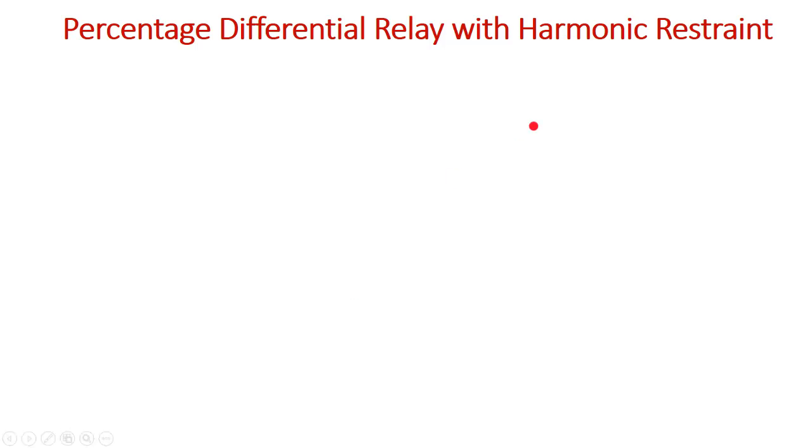What is this harmonic restraint? It is nothing but developing more restraining torque by using the harmonic content inside the inrush current.